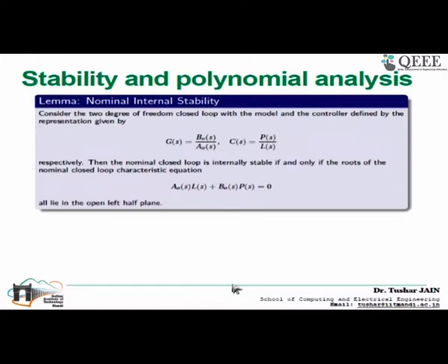So we'll start our analysis. First we show that if all the poles have a negative real part, then the system is asymptotically stable. If you recall from the very first S plane I drew, there were the real axis and the imaginary axis, and I was saying that whether it is a complex root or a real root, I am concerned only with the real parts.